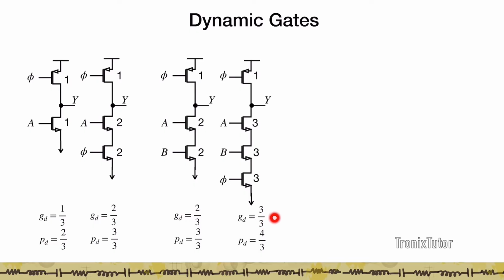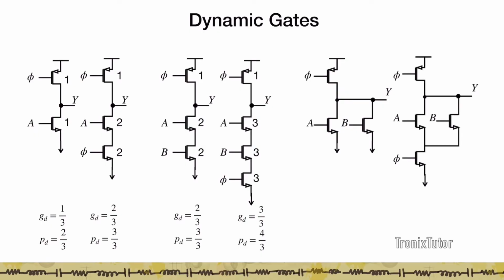Again, these are less than what you would get in a NAND2 gate in static CMOS fashion. Finally, if you look at the NOR2 combination, it has a pull down similar to that of the inverter, and so in a footed case also the pull down logical effort is much less.